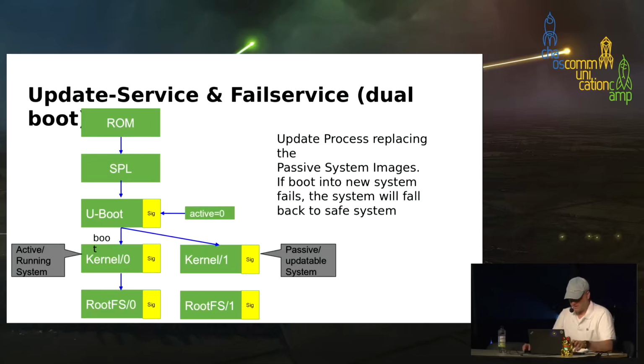Of course, you see here a variable, active. So active is the system 0, which shall be the active one. Of course, it would be necessary to sign this data as well. So we would juggle with some scripting in U-Boot, with those scripts being signed themselves, and just replacing one script by another script. So if you've got experience with such scripting, you can tell me later if it's working, as I think.